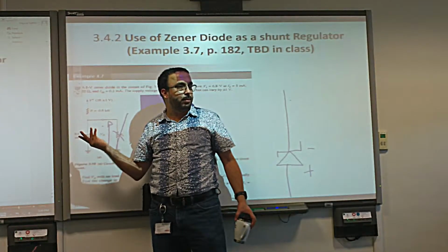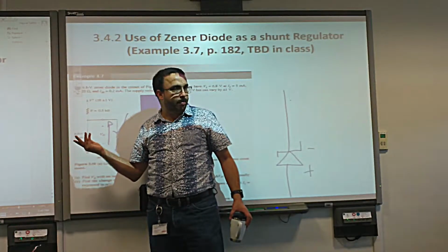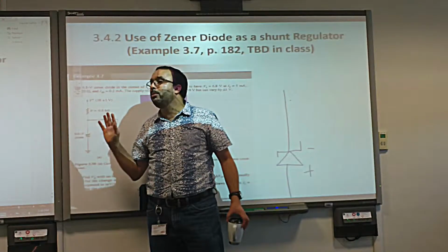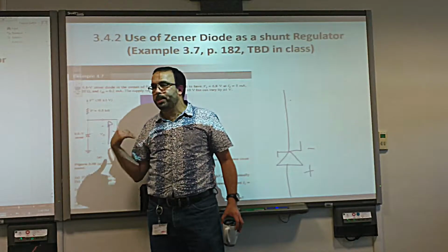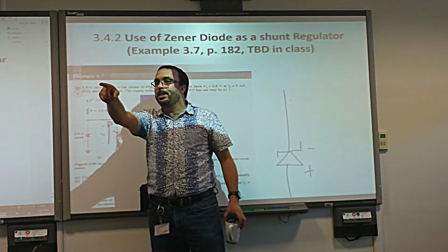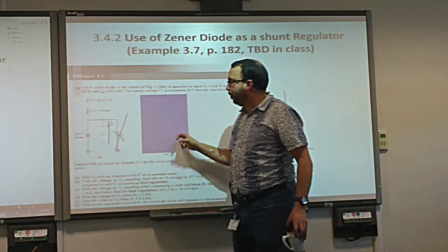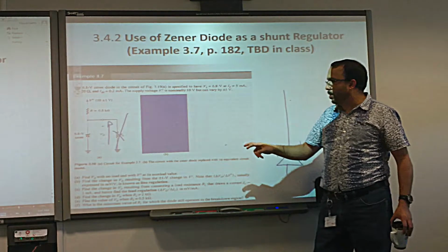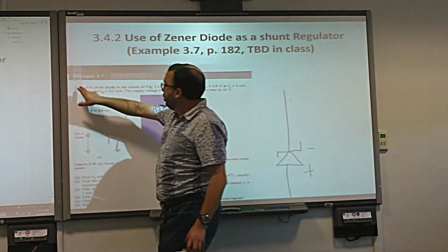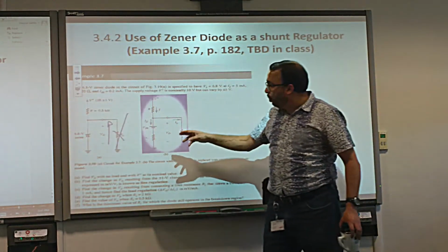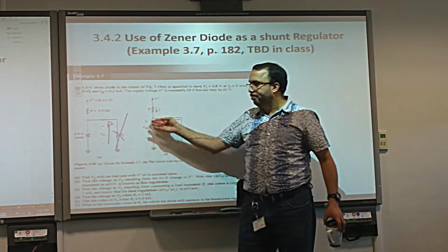It's not necessarily. Do you understand? Make sense? Yes. How do we study this circuit now? First, replace the diode by a battery and resistor. Very good. So the first thing, she's smart because she saw this, but that's good, yeah? The first thing is to replace the diode with a model.